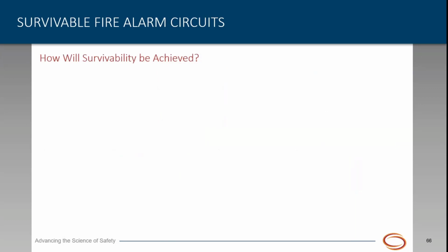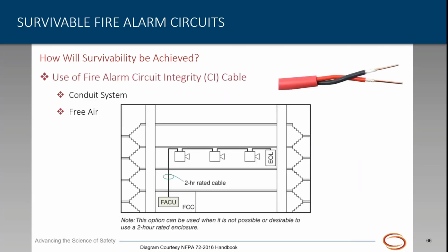Our last question is, how will survivability be achieved? Will you use or decide to use CI cable? And if so, will you need a conduit system, or can you run it in free air? And our next suggestion will give you a few design considerations along those lines.